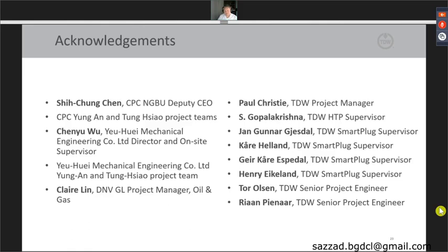Mr. Rahul Shah would like you to throw some light on annulus pressure. Yeah, so like you saw in the animation, the annulus pressure is the pressure that we have between the two plug modules. Our system is a double block-and-monitor, so we keep a pressure of typically 50% of the isolation pressure in the annulus. And there are two reasons for that. Number one is that we want to have differential pressure across each plug module. So the first plug module, you're sitting with about 50% differential pressure, and you also have 50% differential pressure across the second module. That ensures the best reliability because you have both the plug modules sitting in self-lock.